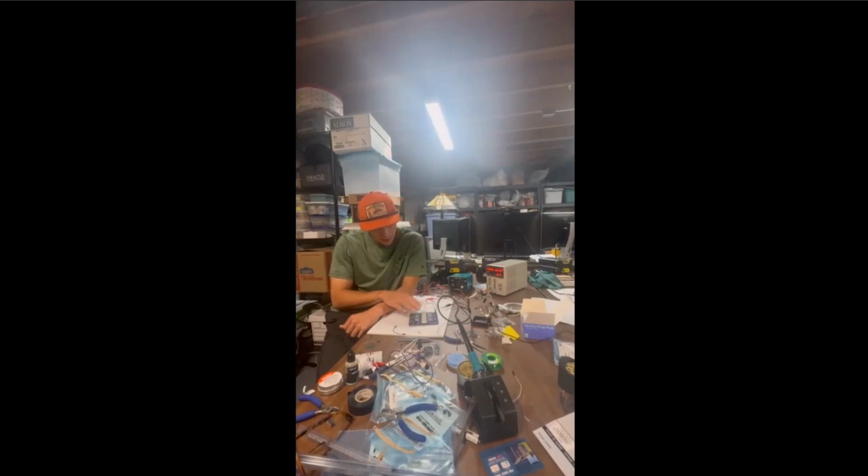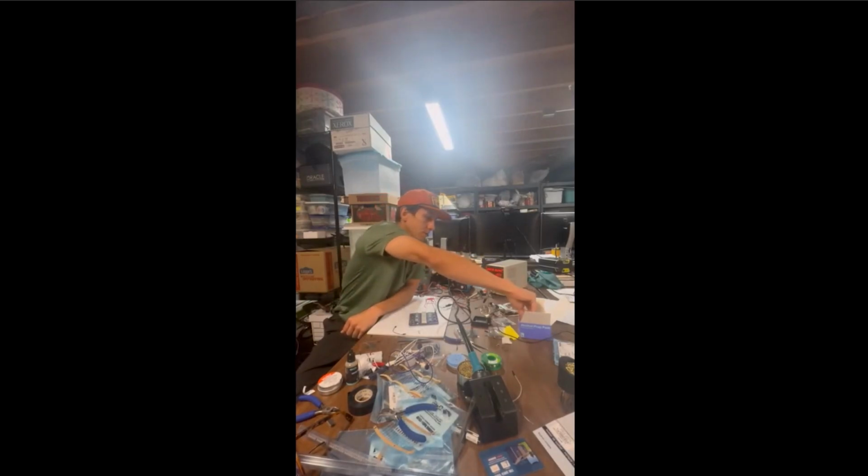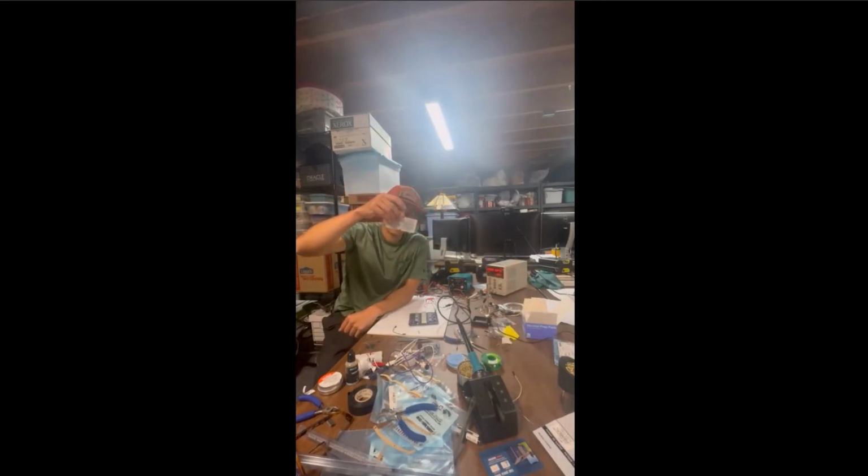One test that I did, I already turned this on and it didn't work again. Turns out flux is conductive, and so I was getting a short circuit. My current was blasting through the roof. Luckily, I have current protection set on my power supply, and it also has short circuit protection. So the moment that I plug this in with power turned off, it'll beep at me if it senses a short circuit, and it was. So did some cleaning with some of these alcohol wipes, and this board looks beautiful.